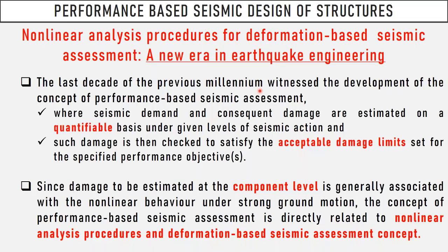And a new era has arisen about 15-20 years ago, and this performance-based approach all started with the assessment process, because we had so many existing buildings, old buildings, or even buildings that had experienced earthquakes. What was their performance? Do they need to upgrade their performance, or are we going to demolish them, or are we going to continue to use them?